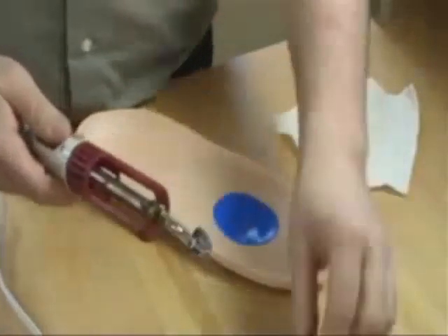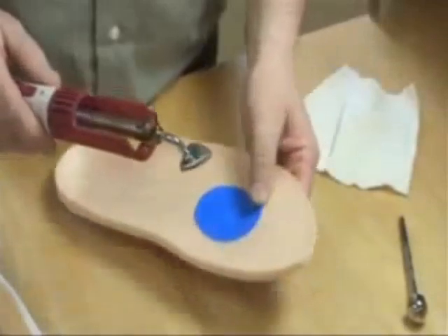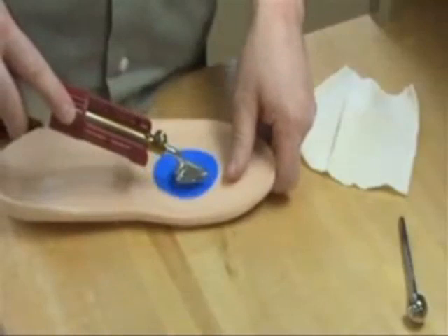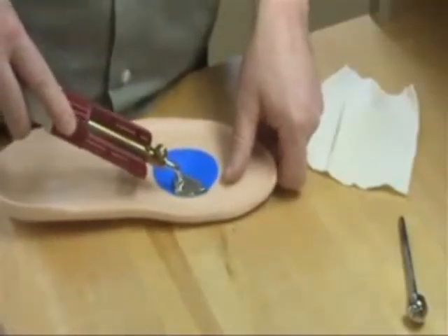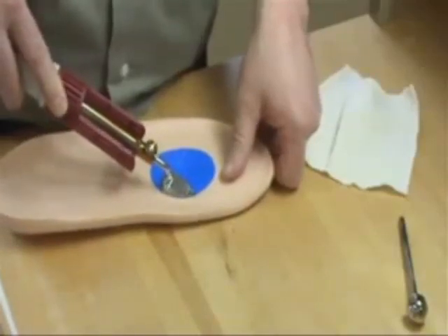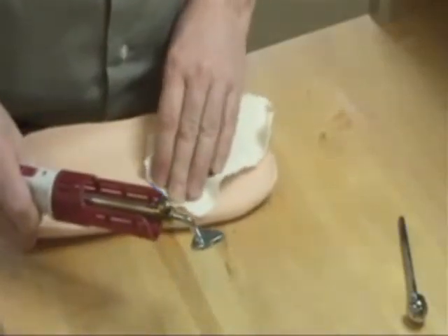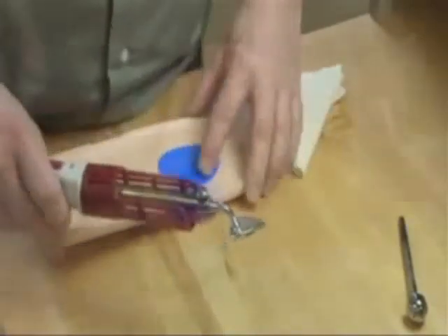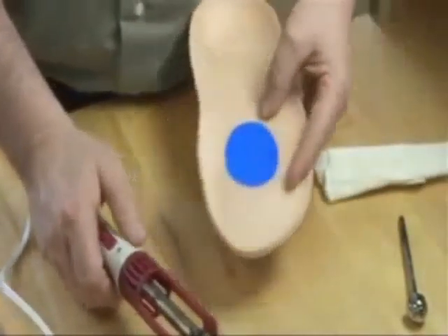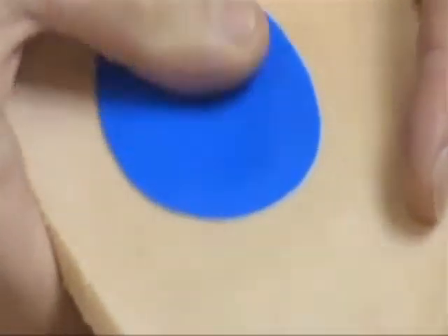Using a small iron is another way to inlay the patch into foam. This video shows a heated iron used for making doll clothing, but any heated smooth surface will also work to iron in the material. When using this technique, make sure that you do not overheat the patch material by heating too long or at too high a temperature, as the patch and/or the surrounding foam may scorch, and the patch components may delaminate. Heat and press in only small sections of the patch at a time. On the patch shown in this video, the edge was inlaid in 3 sections.